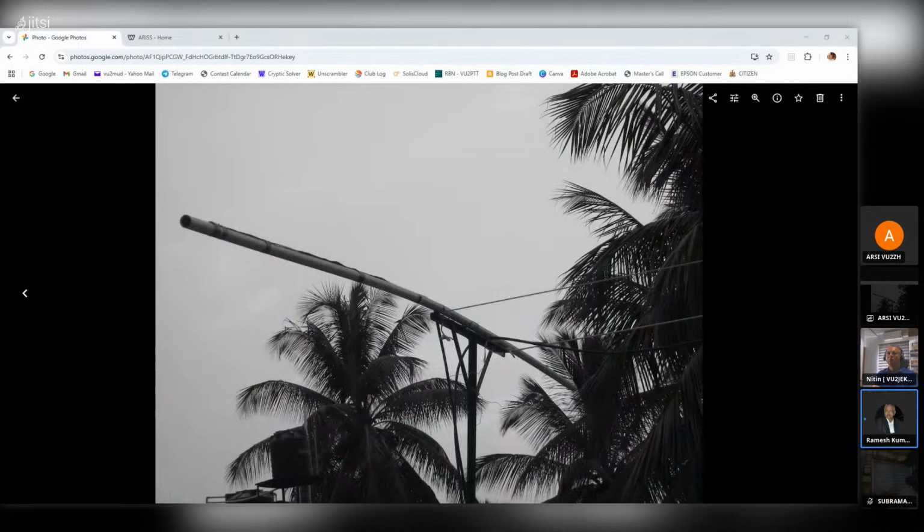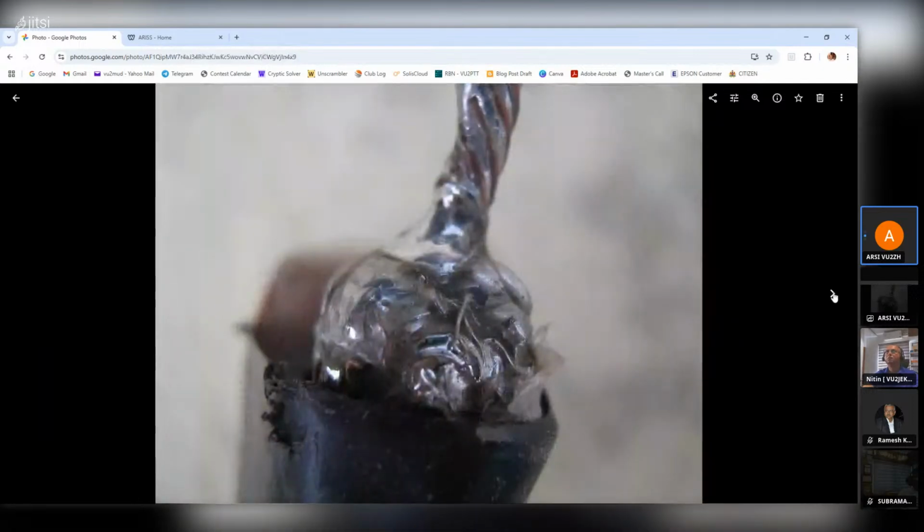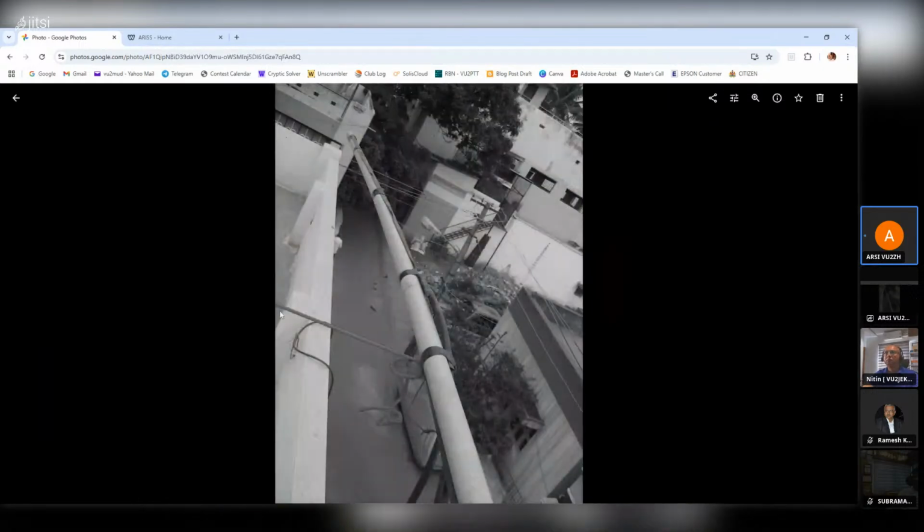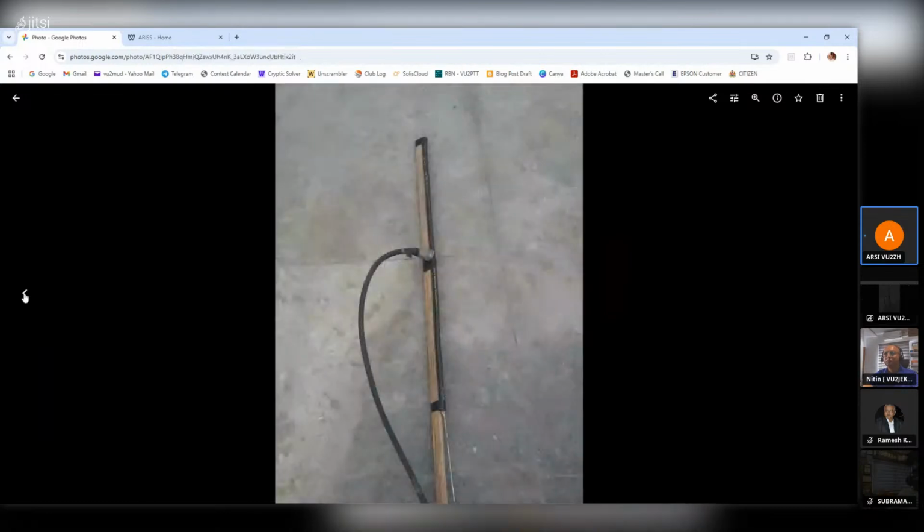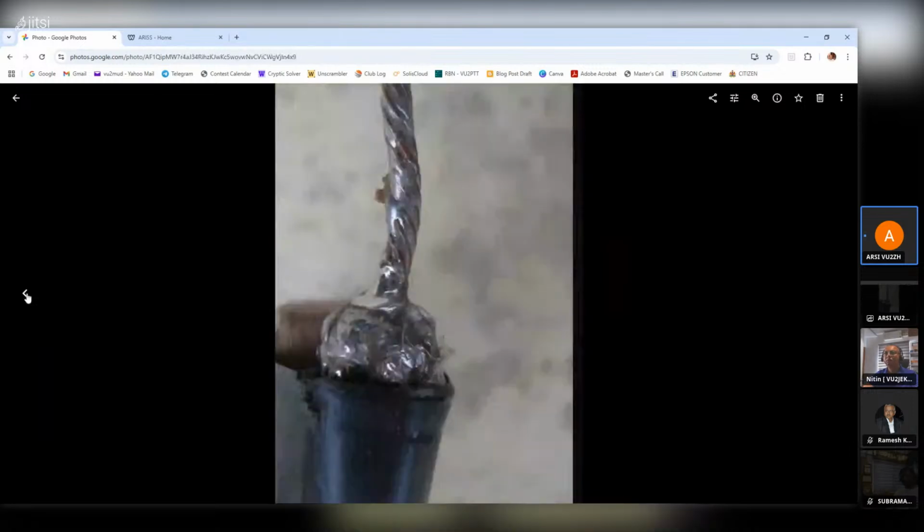This is the picture of my Slim Jim made out of TV ribbon that was taped onto a PVC pipe, and this was laid down horizontal instead of vertical. I was able to work ISS, VO-52 and a few other satellites. And this is the bazooka, I just remembered the name now. This is the bazooka that I had made for UHF, mounted vertically.